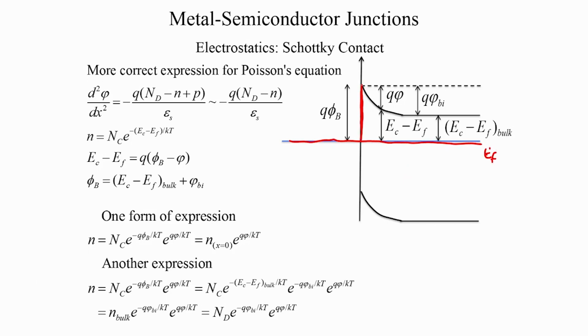So, the Schottky barrier formation, and then that is your conduction band. The conduction band bends and then flattens out after some x equal to x d. So, that is the picture we are looking at. Let us mark that point x equal to x d somewhere there, and everything in the middle here is the depletion region.